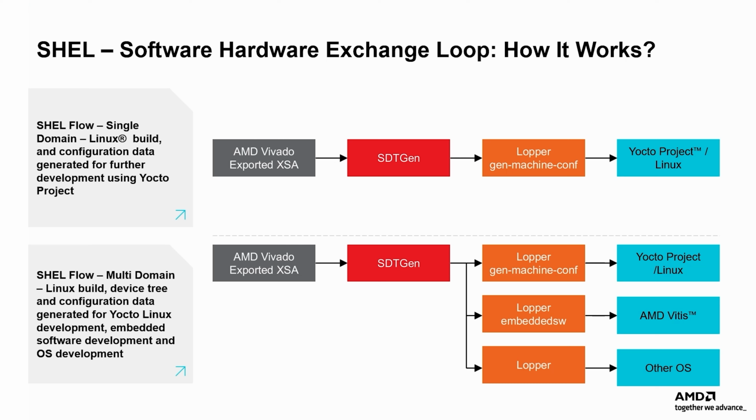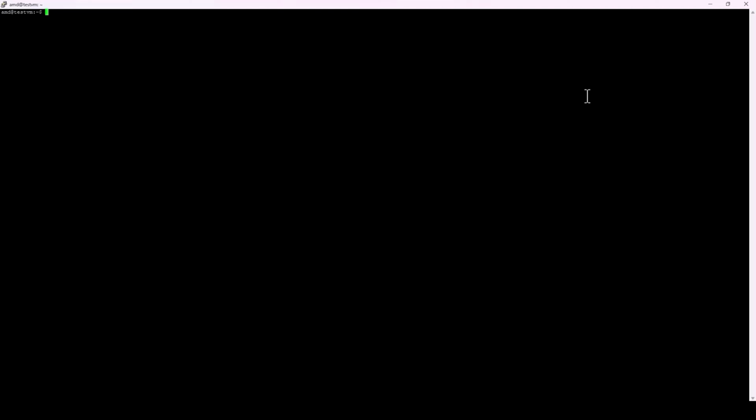After the OS build and configuration information is configured, specific customizations can be made within the Yocto Project ahead of generating output products that can be used to boot the board. First, an XSA file is created from a pre-built Vivado tool project from GitHub. Feel free to use your own XSA file from your own project if you are following along. The example project showing the VEK385 BRAM GPIO timer demo is available on GitHub.